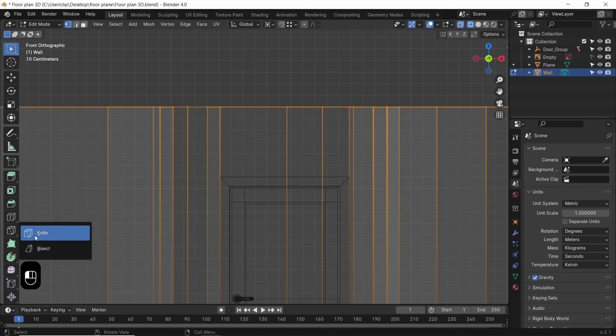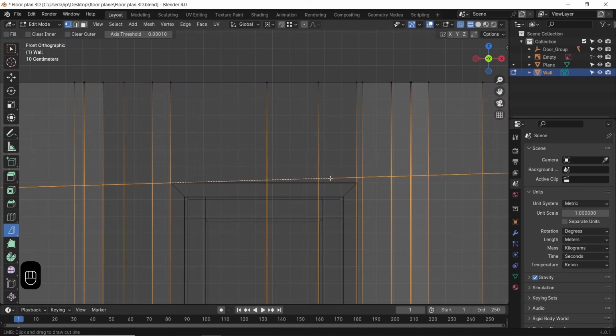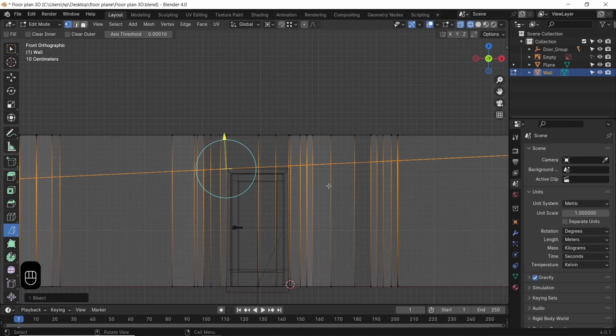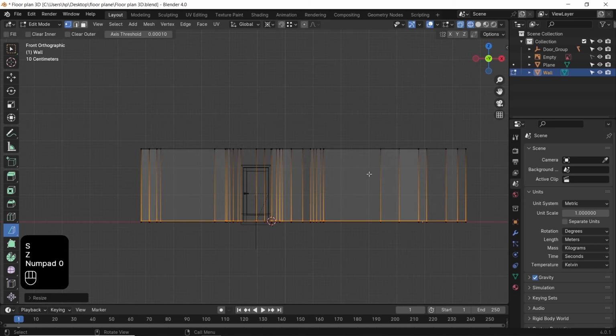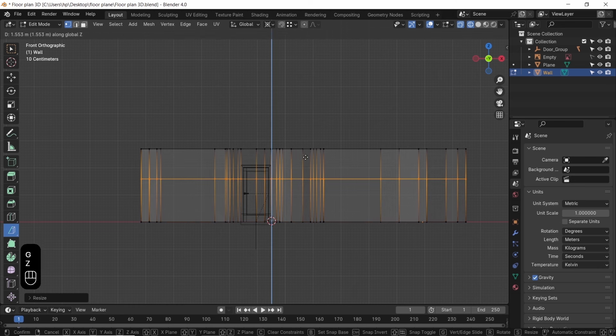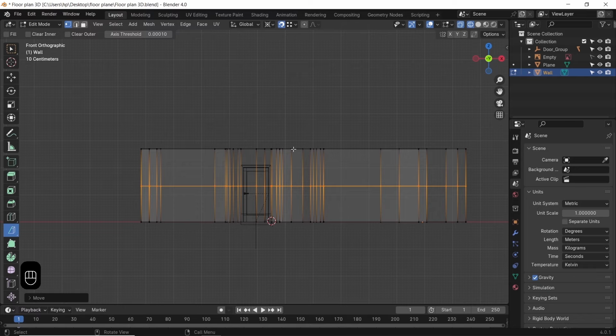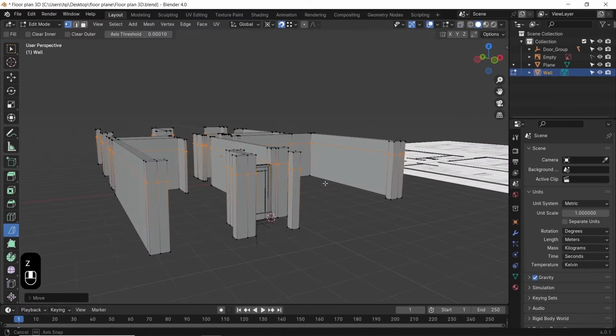We also need to select all in edit mode, so hit A to highlight all vertices, then cut it horizontally. You can cut in any direction you want, cause while the cut point's still selected, you can just hit S to scale them on the Z-axis by 0 value. Again, hit S, then Z, then 0. This will level any set of vertices on the same height. We can after that move it with the snap to the door's border.